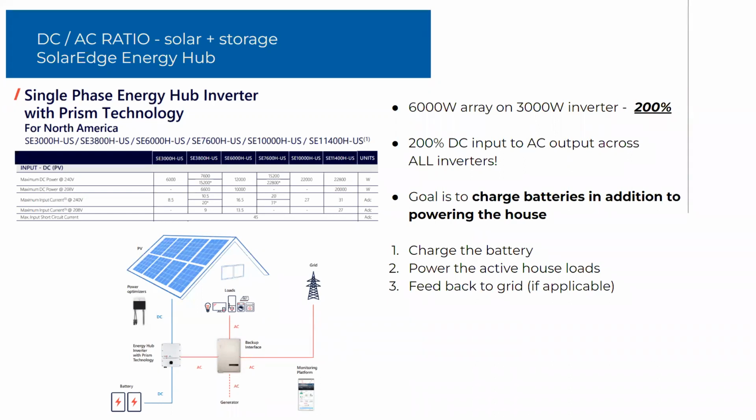However, if I'm doing self-consumption, or if I am living in a case where I don't get net metering, I may need to charge the battery after every single night. In that case, in order to build back up that depleted battery that I used overnight and charge the loads that I'm using today, I'm going to actively want to add more PV.